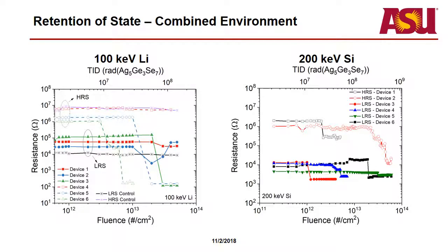For these tests, these devices were put in the nanoplanar, and the nanoplanar has an actual probe station inside. So we put it on the chuck, we probe each individual device, and then we raster scan the beam over the device. For these tests, we just programmed the devices, and then we kept them probed, but we did not apply a bias. We hit it with radiation, and then we did a 30 millivolt IV sweep in order to read the state.